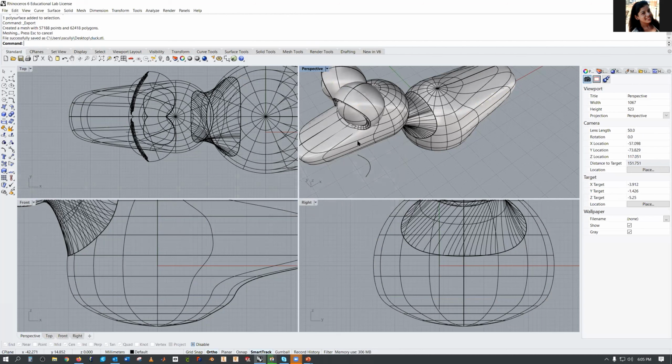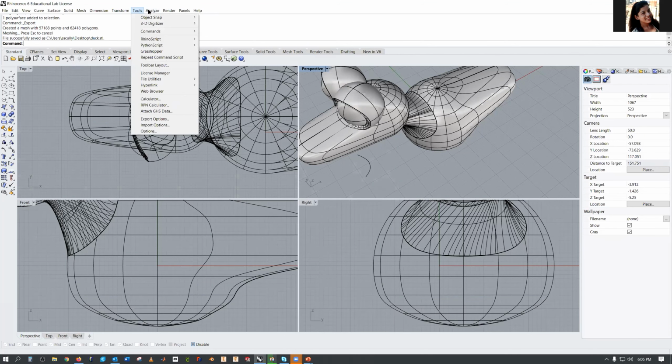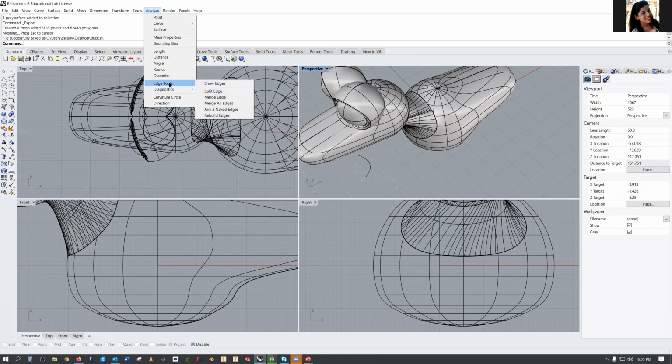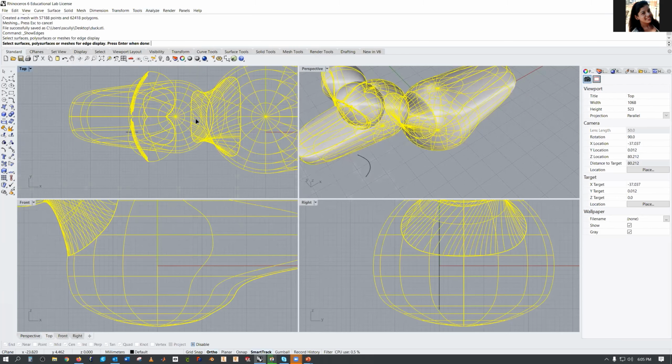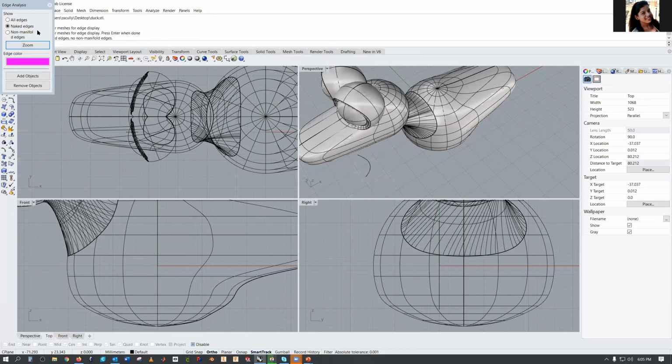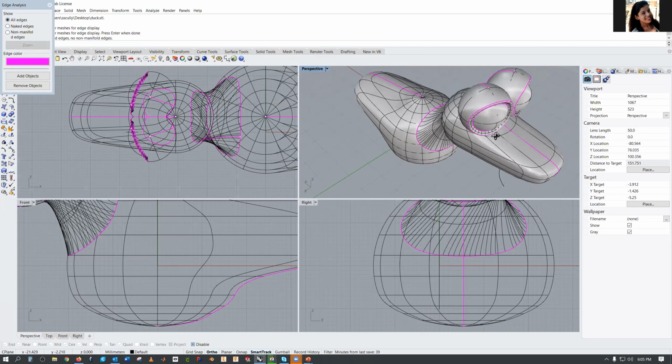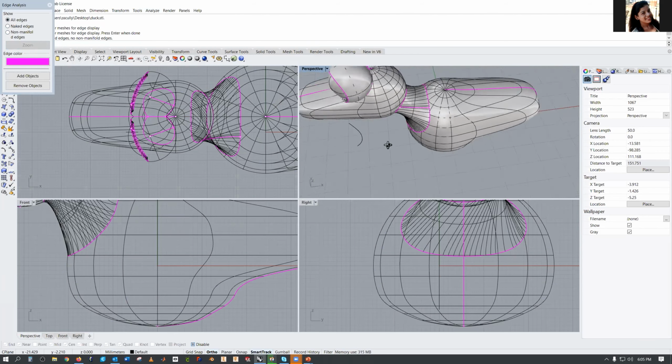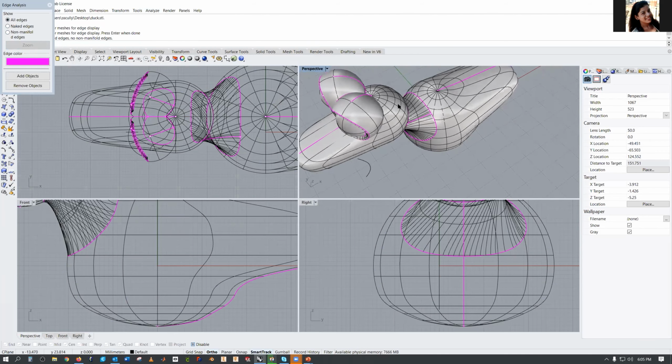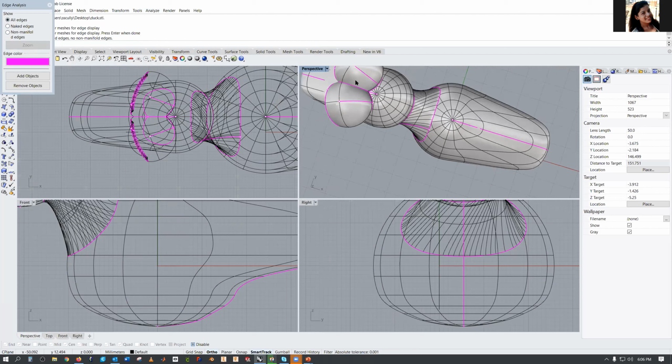It can happen. So there's a couple ways to fix those things, and that would be in your Analyze Edge tools. So I can show edges on this object, and I can show this is all the different edges. So unlike maybe a more geometric shape, where this face obviously meets this face, here your edges are going to be a little bit different. So you can see where all the seams are in these objects, as well as where they maybe connect.